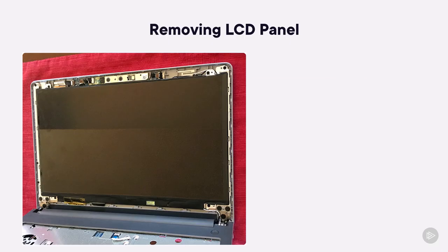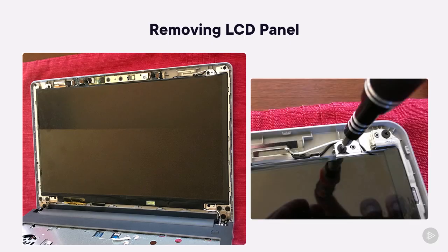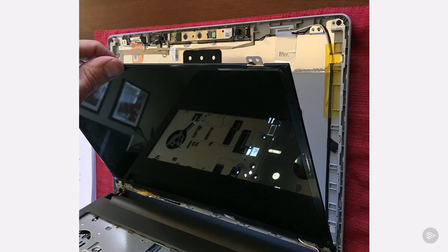The next step is to unscrew the fasteners holding the panel to the display assembly's outer shell. This model features 4 such screws. Be careful because once the last one is removed, the panel could flip forward more quickly than you intend. It's best to have your hand on the top edge so that you can guide the panel forward, make sure all the wires are free, thinking here about the power and signal connector, and then lift it up and out. This is a fairly typical example of how we can access the inverter and digitizer.